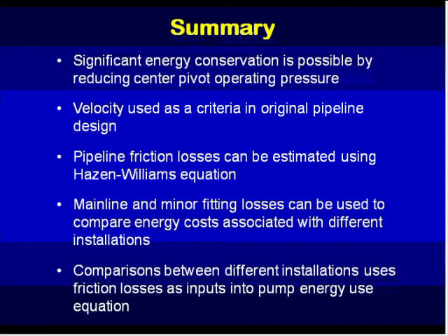But the sprinklers are going to be operating there, and sometimes it's difficult to do it while the system is actually running. So my sense of it is that the best scenario would be to have 3 or 4 that one would put on the system in different places, and then start the system up and record those values afterwards, and then later go back and remove them.